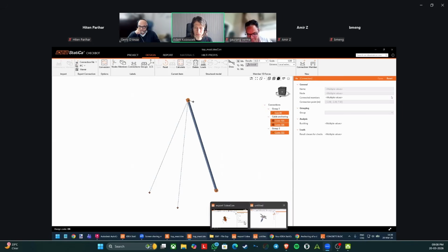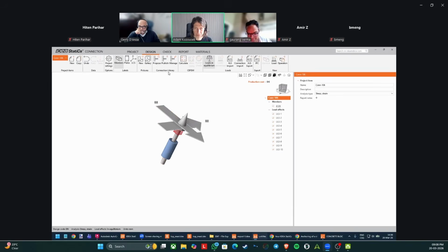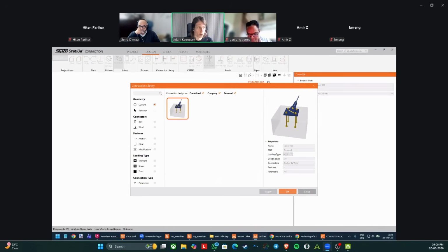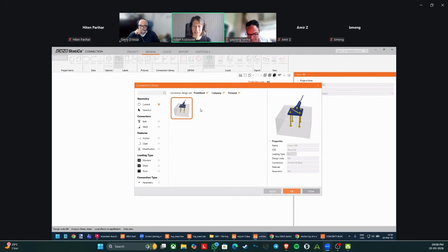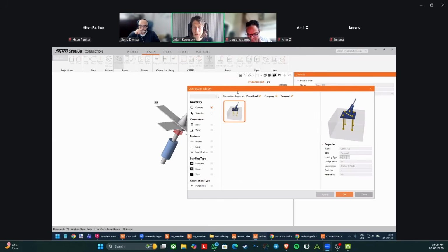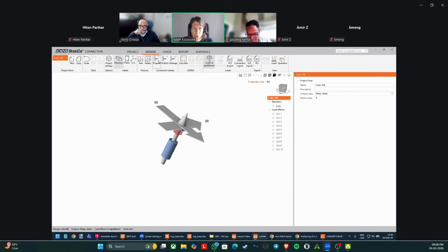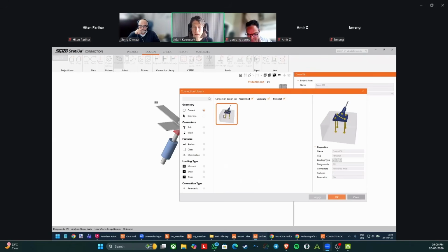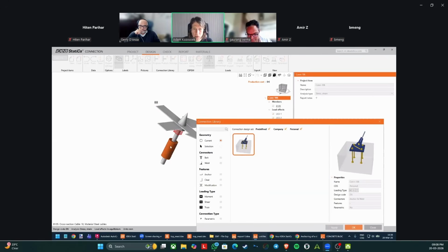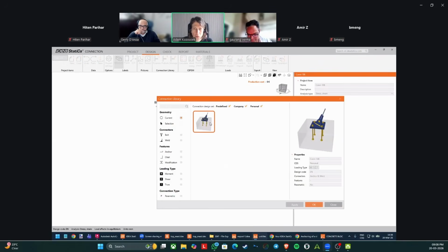All right. So on my second screen, in the meantime, I published the template into my library because I previously deleted it. So this is how it works. Once you push the propose button, it reads the geometry, so the members that you have, and it looks for suitable templates in your connection library.